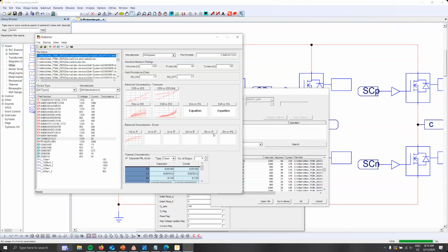All of these we find either on the data sheet, or we request the manufacturer to create a model or send us the adequate information. But this is practically the information that we need, right? We have VDS versus IDS so that we can get conduction losses. Then we can go towards turn-on energy and turn-off energy, from which we can calculate losses. We can also take into account the gate resistors from the gate drive circuit, and calibrate our losses according to this.